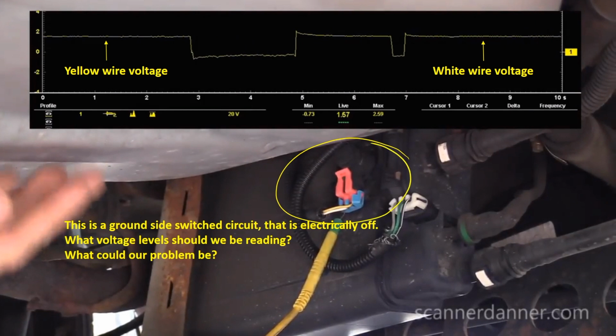It's an evap vent solenoid. Pretty typical controlled component. It's a 2-wire device, and I'm doing some voltage measurements just real quick on both wires. And this screen capture at the top, it is the lab scope in a graphing meter mode. I only picked that because it's on video, I can show it easily, and then I can show the still frame capture on one.